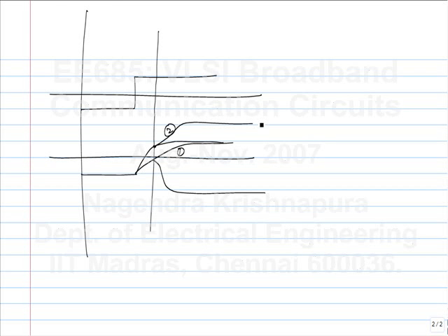You can't change the performance beyond that. That is the technological limit. One measure of technological limit is FT, the transit frequency of the transistor. That is the ratio of the transconductance to the capacitance of the transistor itself. If a transistor was loading another transistor, that would be the unity gain frequency. Similarly, you will reach maybe not the same frequency, but something related to FT, because the transistor will start loading itself. Okay, now what's the effect of M5 and M6?